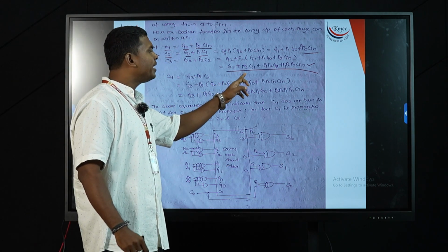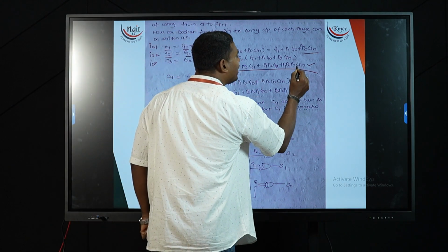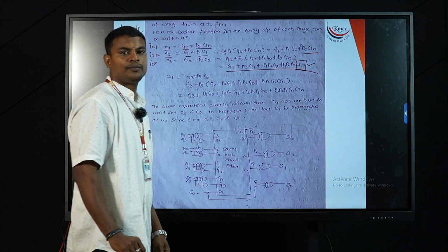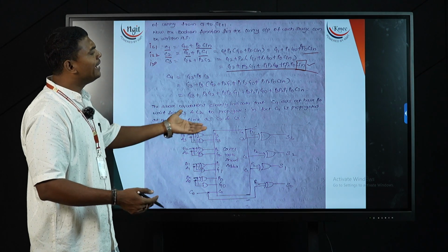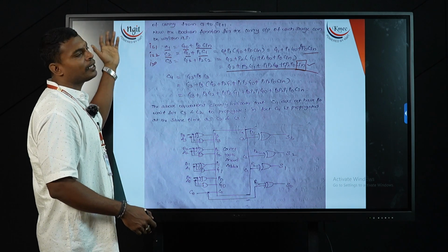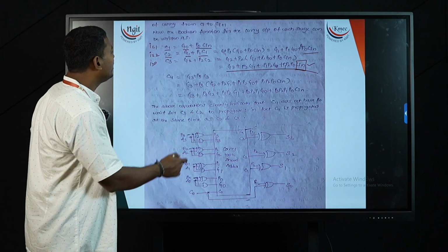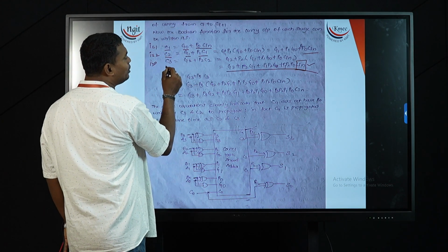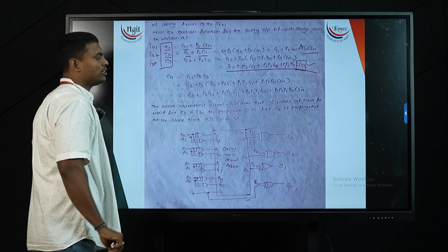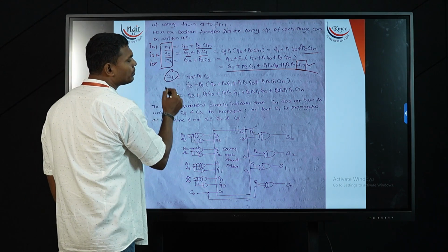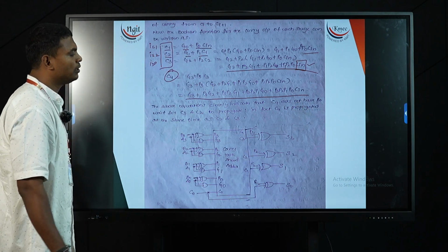But it is not depending upon either C1 or C2 or C3. It is just depending upon my initial stage carry in only. Means I should not, or I cannot wait for any kind of carry to be generated and propagated. I should just see the initial stage carry itself. So with this expression I am clear that I can generate my sum values without the help of C1, C2, C3 or C4 also for the next step. You can observe clearly the expression doesn't contain any C1, C2, C3, C4.